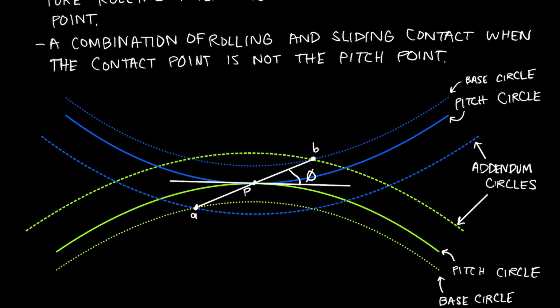And then we need to divide that by something to get the number of teeth in contact at any given time. And since this line, AB, is tangent to the base circle, we can use the base pitch to calculate our contact ratio. So let me write all this up, and hopefully seeing it will help it make some more sense.